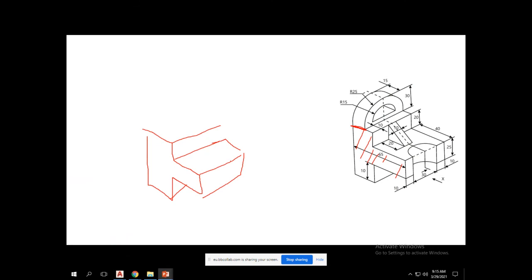Now you come to this surface and draw a half circle, and then make press pull. Clear, guys? Then you come to this one and press inside, and it will make a hole, right? I said press pull means you are pressing inside, not on the edge.